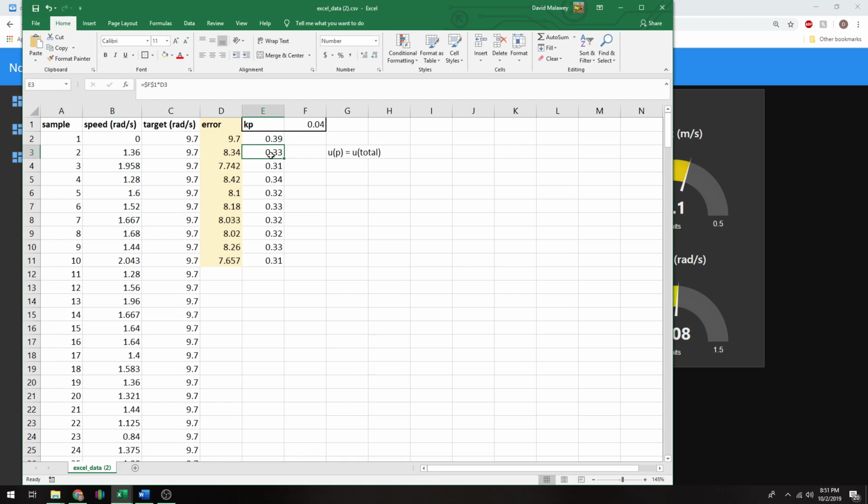In this case, we're only giving about a third of the voltage, and it's just barely enough to actually drive those wheels from a standstill. Since the motor's spec'd at 12 volts, it's not very typical to ask that motor to even move at all under load when you're only giving it less than half of the voltage.